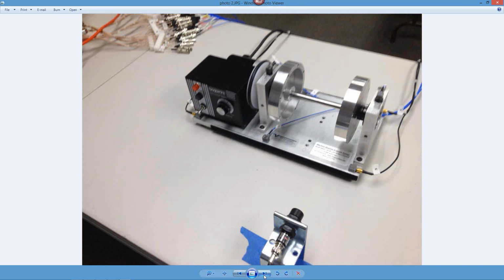So here's another view of it. You can see the tachometer a little bit better. This tachometer is a BNC-based tachometer, so we treat that signal just like a vibration signal coming from an accelerometer. So this goes into the analyzer along with the BNC connections from the 8 accelerometers. So total of 24 degrees of freedom in our shape table from the accelerometers, plus we use the tach signal to locate the first order or the running speed of the machine.